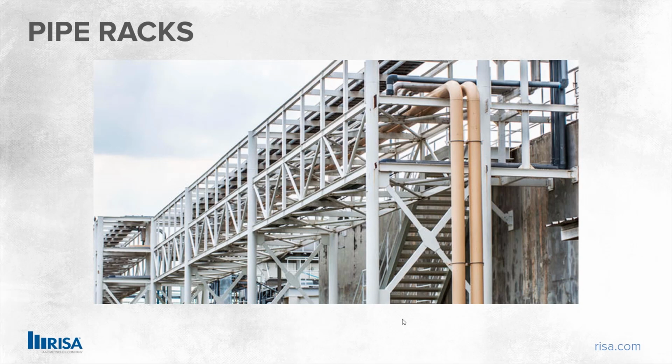We'll get more into this, but pipe racks are actually non-building structures that have similarities to structural steel buildings. And that's going to help us classify this structure in terms of finding the correct wind loads and seismic loads per the applicable codes.